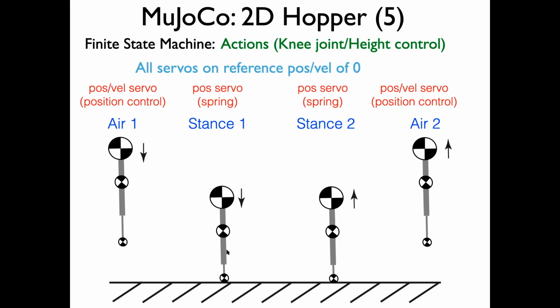So the goal here is, I'll set a spring. Let's say the spring constant is 1000 when it's compressing. If I suddenly change the spring constant to a bigger value, greater than 1000, let's say 1200, then it'll actually bounce off much higher, right? Because the spring constant has changed in the retraction phase. So I'll set a high gain, only a P servo, when it's in touchdown. That way I can get the spring action. But once it's in the air, I'll turn the velocity gain on, and that will damp out the oscillation. So it'll be stuck at a position. It won't really wobble back and forth.